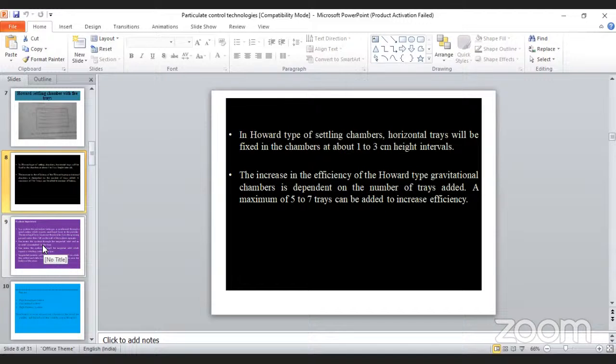You have to remember 3 points. According to the formula, otherwise according to Stokes law, which is developed for the fine particles removal from the gas stream. According to that law, the free falling velocity is proportional to the diameter of the particle and the density difference between the particle and the carrier gas, and inversely proportional to the viscosity of the gas stream.